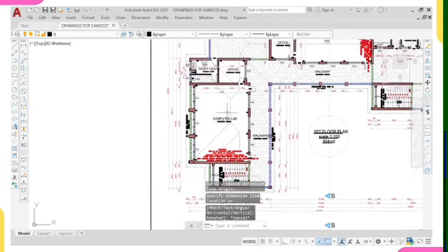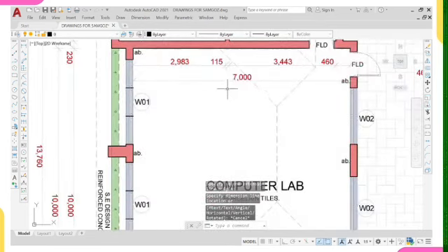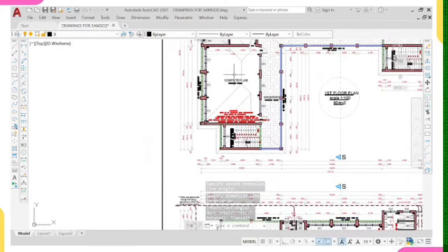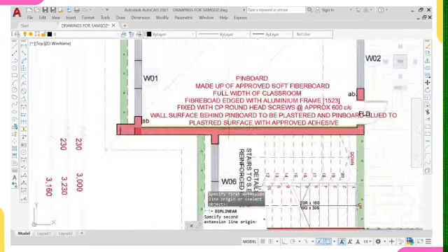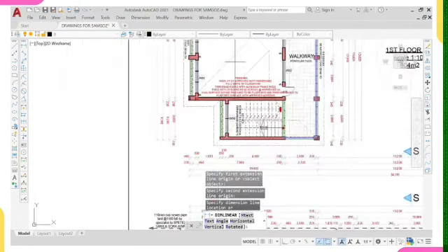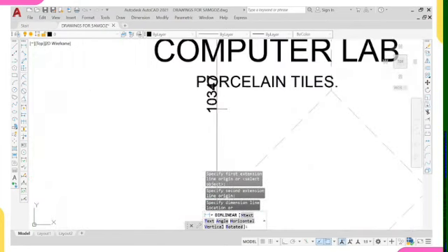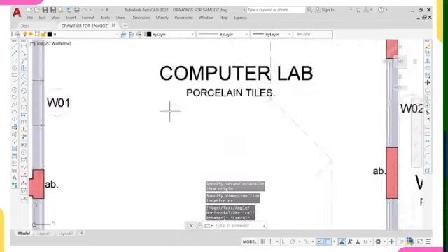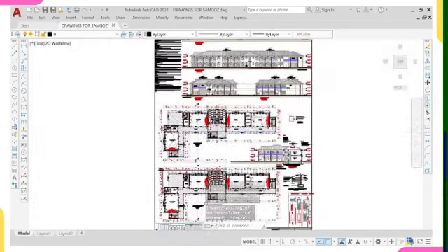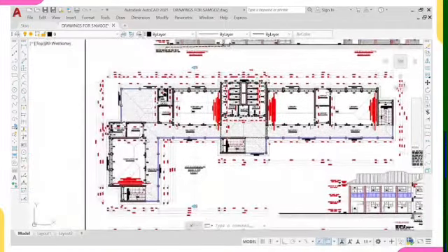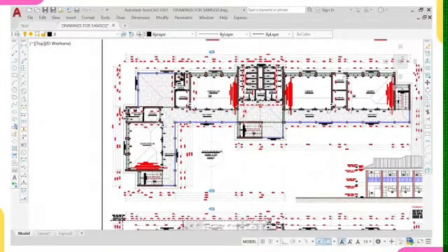This is one of our recent projects. Look at it, 7.2 meters. Let's also check the length from here to here. Here the span is 10.3 meters. So the uniqueness of this design is that, one, it has an expansion joint because of the length of the building, and then some of our beams are spanning above 6 meters.